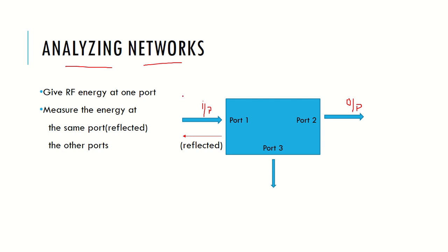So if you see voltage and current at high frequency, we saw in the general solutions of transmission lines that the voltage was not a single quantity. It contained a combination of two voltages. One we call the incident voltage and the second we call the reflected voltage. So when I talk of high frequency hereafter, the voltage and current are no more single terms. They are a combination of two or more terms together. We call voltages incident voltage and reflected voltage. We can say the current might get transmitted, or get absorbed in the network, and so on.